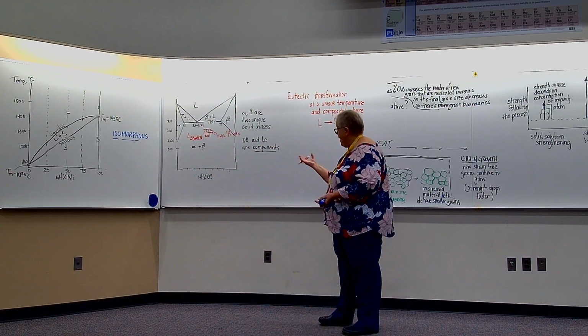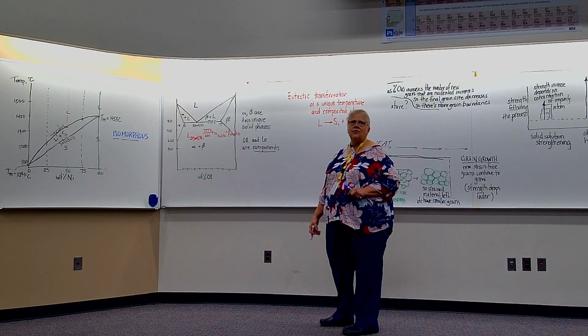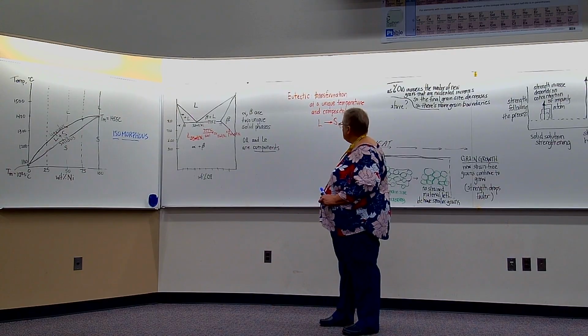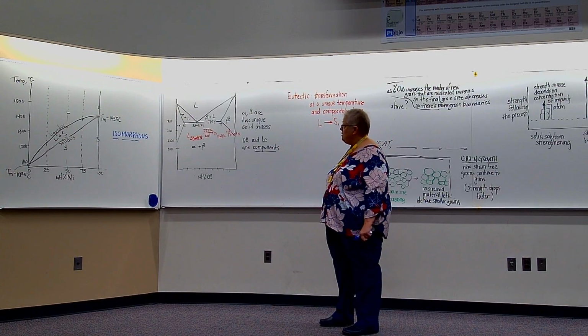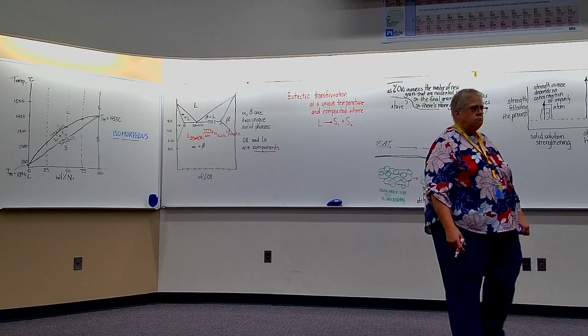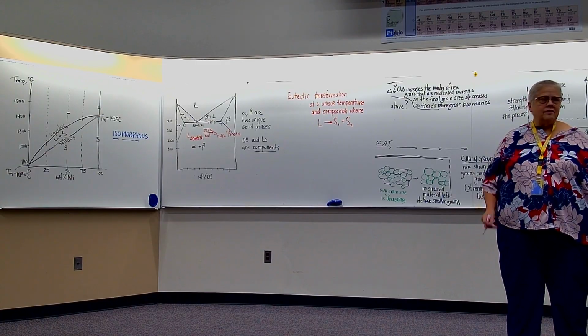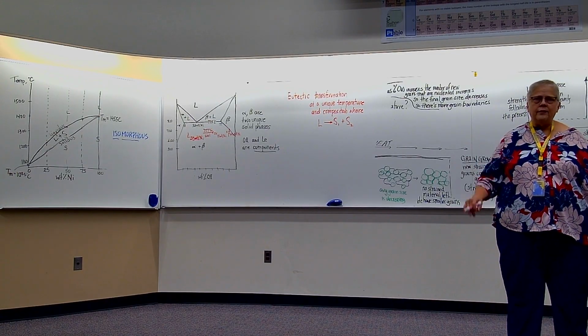So for that phase diagram, that's the eutectic reaction or eutectic transformation. It's sometimes called either one. But note that I have a liquid that's transforming into two different solids, all at one temperature. All of that's happening at one temperature.